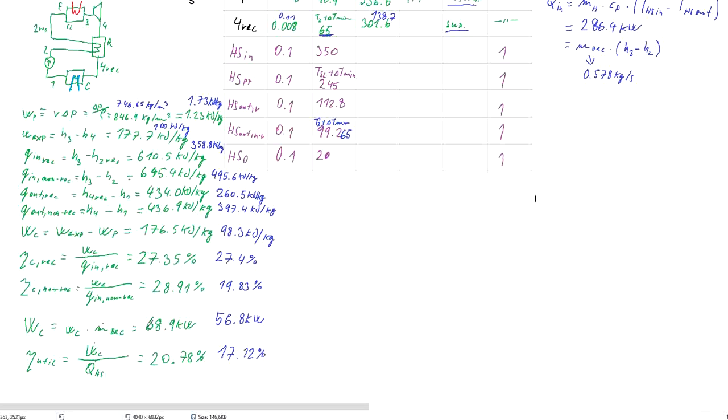When we use the working fluid Toluene, we get the best performance, work of the cycle almost 70 kilowatts and nearly 21% utilization efficiency. Just the Toluene has some application issues as it has, for example, issue with the lubrication of the components.